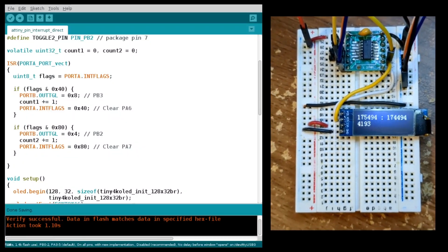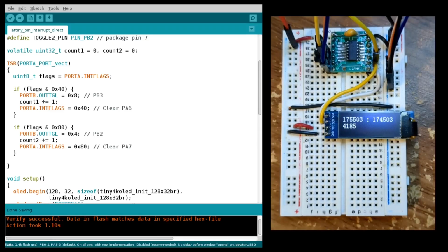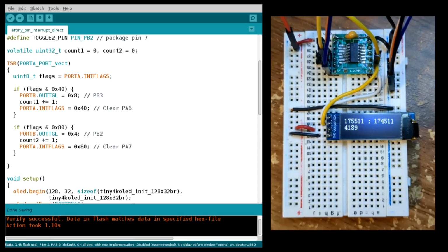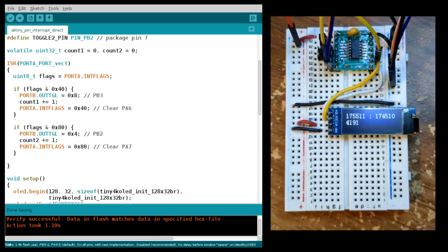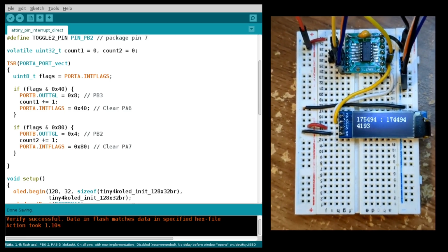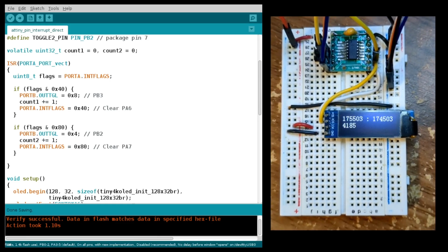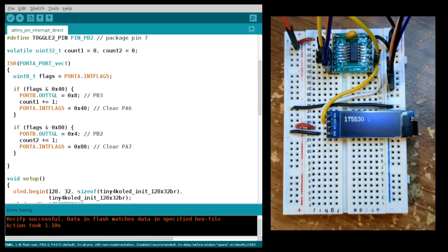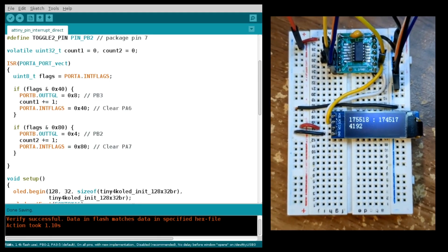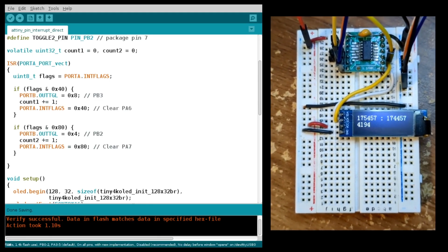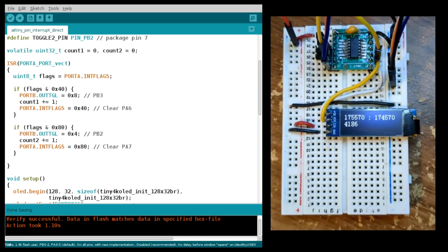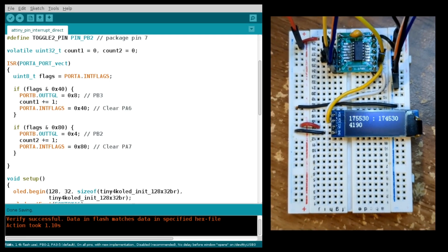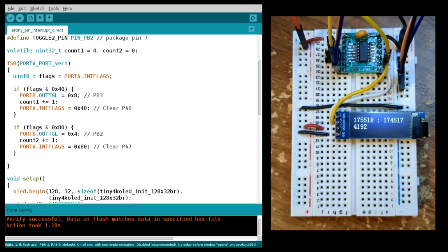Returning to performance for just a moment before we end, my previous video, linked below, showed 2 external pin interrupts using the standard Arduino attachInterrupt API. It achieved about 96,000 interrupts per second total on an ATtiny 3224. I decided to change that program to use direct interrupts for an apples-to-apples comparison. You can see it running with 2 times 175,000 or 350,000 interrupts per second. That's a direct comparison between standard and direct interrupts on the ATtiny. You can see the interrupt handler on the left checking both pin interrupts.